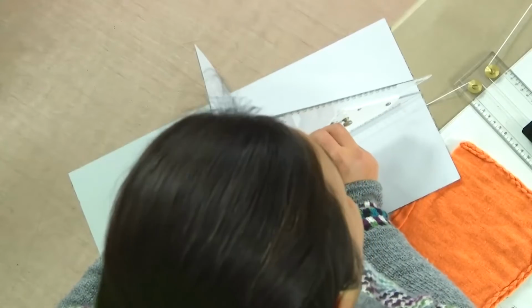Now, if I have a line which is inclined to both HP as well as VP, whatever that line is, if it makes an angle with HP and VP both, the sum total of the angles that it makes with HP and VP will remain 90 degrees. Now, how do we draw that? How do we draw this kind of projection? We could start by doing this as well. However, that would not be the right way, or it might be difficult to draw.